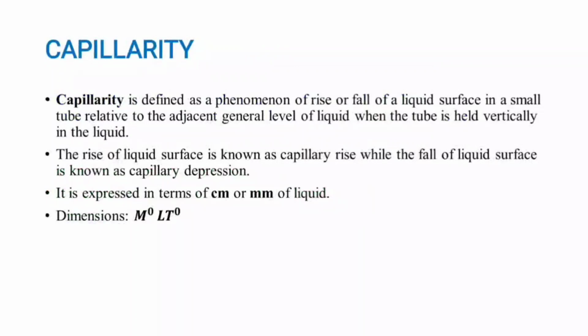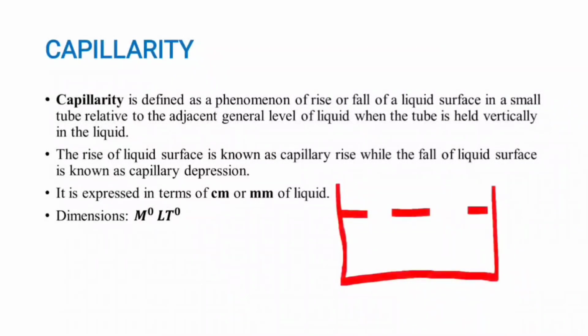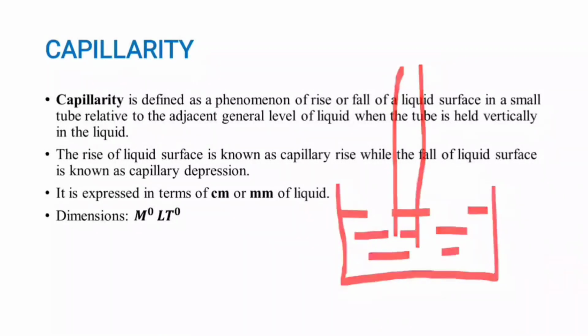The next topic is capillarity. Capillarity is defined as the phenomenon of rise or fall of a liquid surface in a small tube relative to the adjacent general level of liquid when the tube is held vertically in the liquid. For example, liquid is present and I insert a capillary tube vertically. If the water rises in the capillary tube, it is called capillary rise.